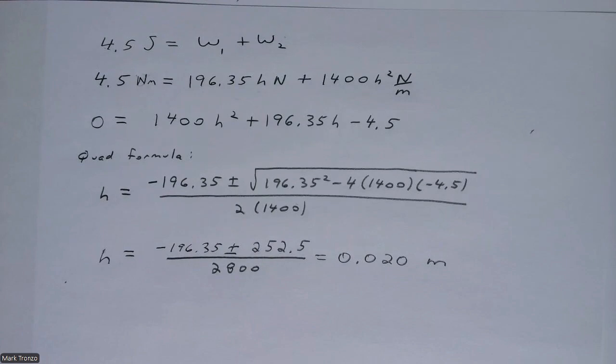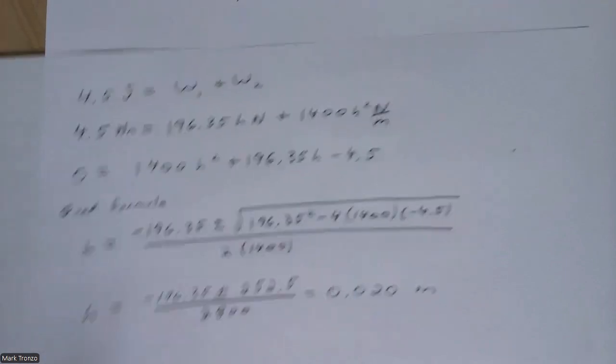Next thing we're going to have to do is find the temperature of the gas. And so we're going to have to use the ideal gas law. What do we have in this case? We have nitrogen, which is an ideal gas, so we can use the ideal gas law. Now, when we go to calculate with the ideal gas law, we're going to need the initial and the final pressure as well as the mass of the gas. And so we're going to have to start with our given condition to find the mass of the gas.